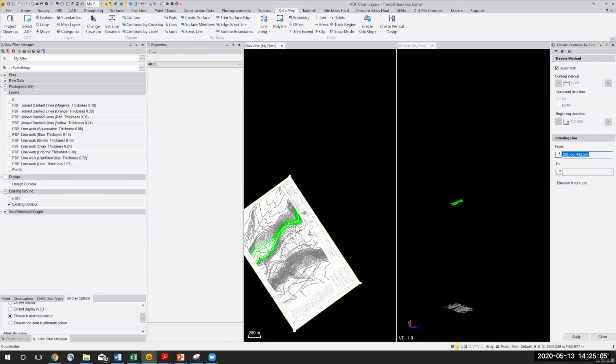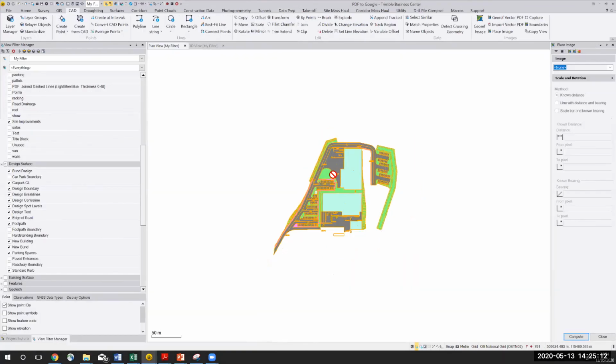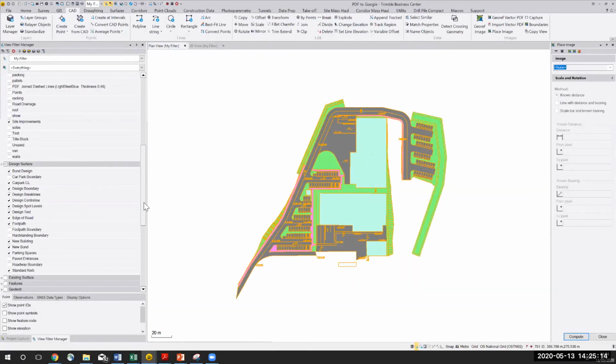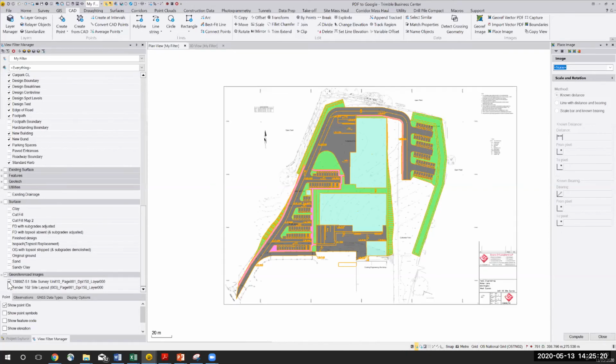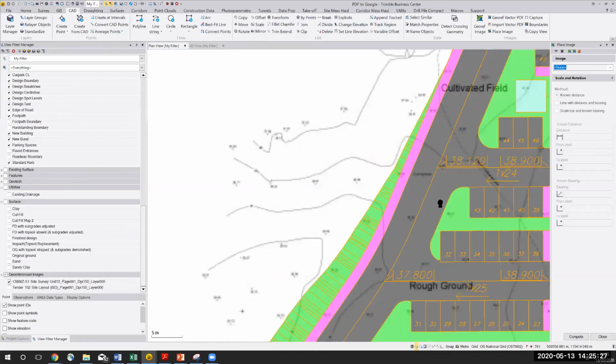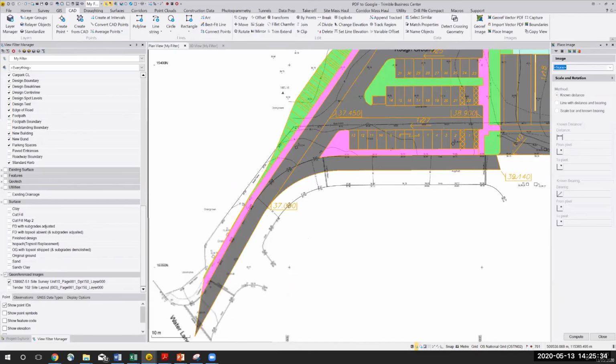And then, so that was basically using a scale bar and known bearing. If I come into this drawing here, this is one where I knew the position, so I was able to georeference the image. So if I turn on the image here, I had some survey marks dotted around the job where I knew the position of. There was some control points somewhere where I knew the grid positions of them, and I could click on these.